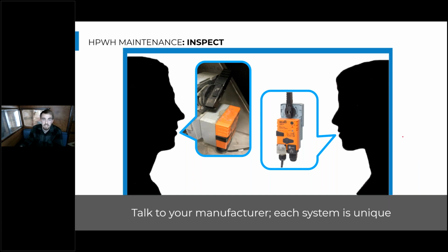So if you see that your refrigerant pressures are at a certain condition during installation, and you do follow-up maintenance and inspection and find those pressures are a lot different with relatively the same air and water conditions, then you'll know that there might be something to look at with your heat pump and something to address, most likely through the heat exchangers, but other components that your manufacturer can more finely attune you into.